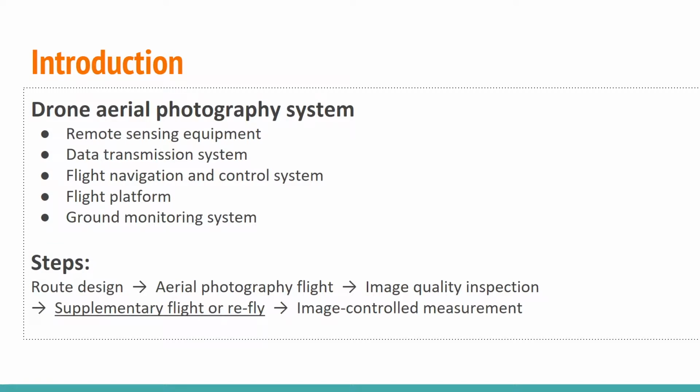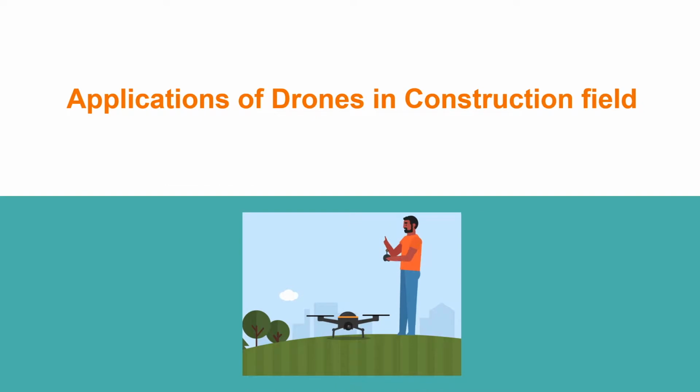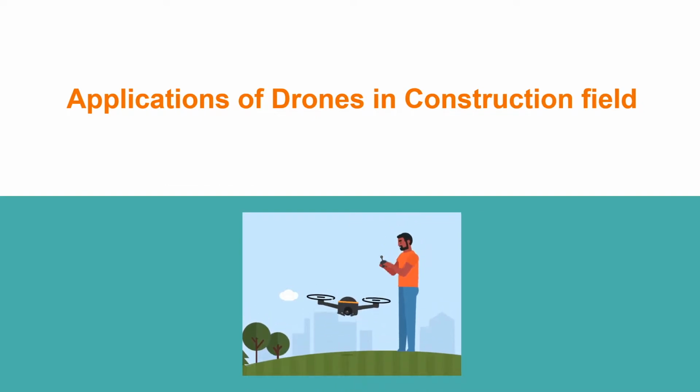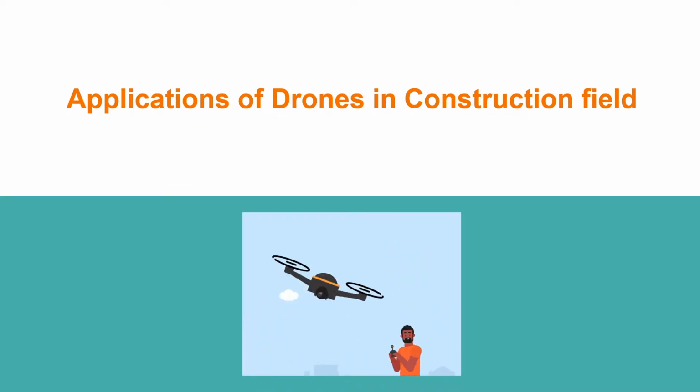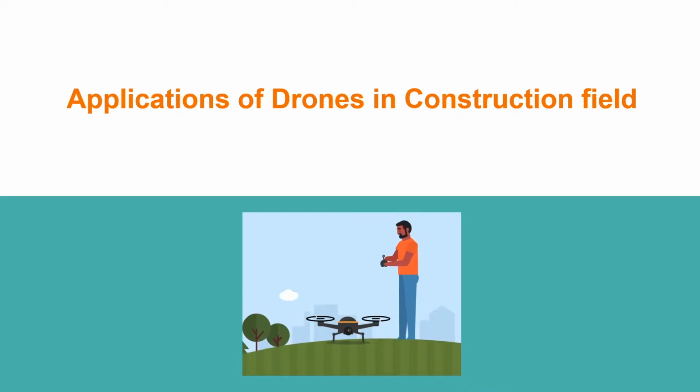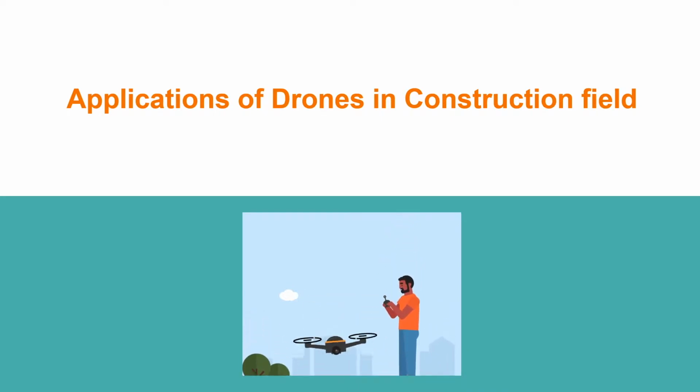And here are some steps we need to go through when using drone to get some images. Route design, aerial photography flight, image quality inspection, supplementary flight or reflight if necessary, and last but not least, image control measurement. Drones is one of the new technologies in the construction field, and I'm going to introduce three major drone applications in the following slides.